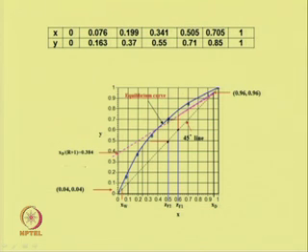As we have calculated, intercept is xD by R plus 1 which is 0.384. So, from this intercept and with the xD which is 96% is given over here, we can plot the operating line. So, this is the operating line for the rectifying section.